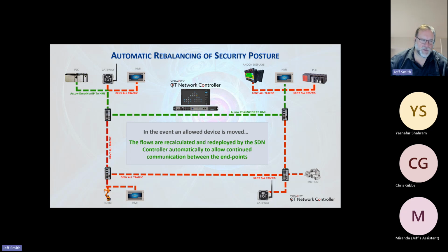So one of the big things that's different, and I think it's a conceptual challenge, if you're like me and you've been doing networking for a long time, traditional switching and networking is largely port based. So you're interested in what port something's plugged into, what VLANs are trunked on that port, what spanning tree is enabled on that port. And if I have VLAN 401 on port 4 and I move a device to port 6 and there's no VLAN tagged on that port, it can't talk. Which in itself is a challenge on a plant floor to troubleshoot. I've run into that a few times over the years.